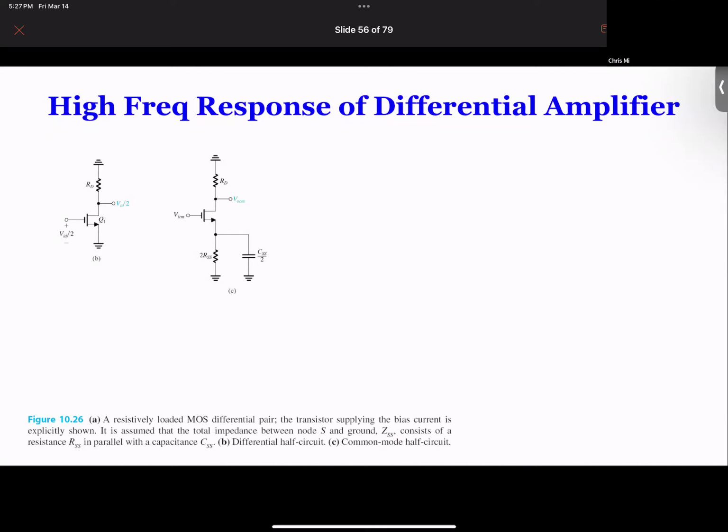If you look at this circuit, you might already know, well, this is not a common source, it's not a common drain, because the drain is not grounded and the source is not grounded. But overall, this is equivalent to a common source amplifier with a resistance as the source. We analyzed that before as well. So we have that. So if you look at the common mode gain,